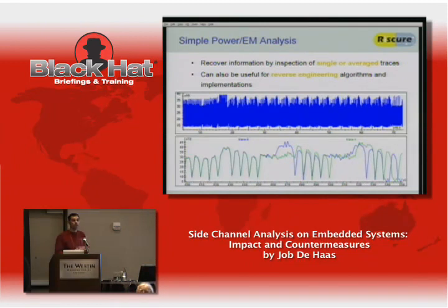And actually this is from a GSM chip. So this is, I think, Comp128. Where actually in the C code you wouldn't see anything, because the people that were coding the C were just creating a table, an unsigned char, you know, a 512 index. But the compiler will make this choice for you. So you actually don't even see it when doing a source code review in C.